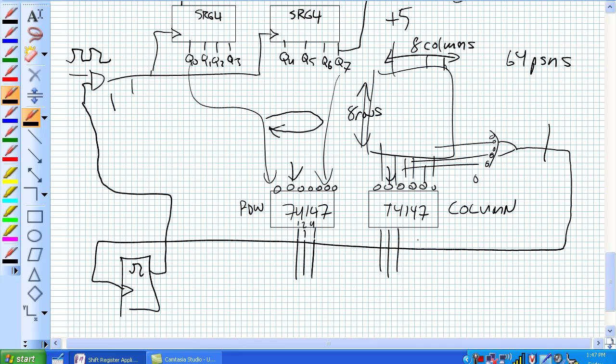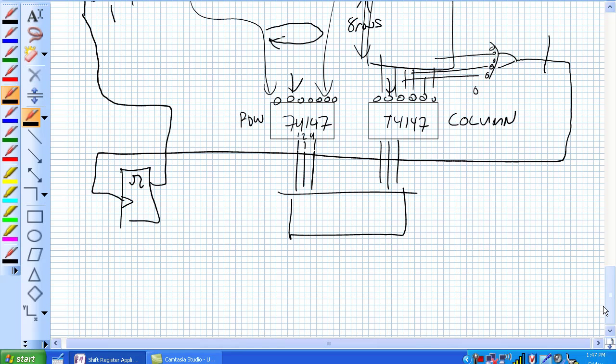Basically, those 3 particular positions are going into, in this particular case, a 6-bit shift register, and they're using a 74174 for that. You could also use an 8-bit shift register and just use the first 6 positions if you wanted to. But now we've got to go ahead and somehow enable that guy with a little clock pulse using another one shot right here.